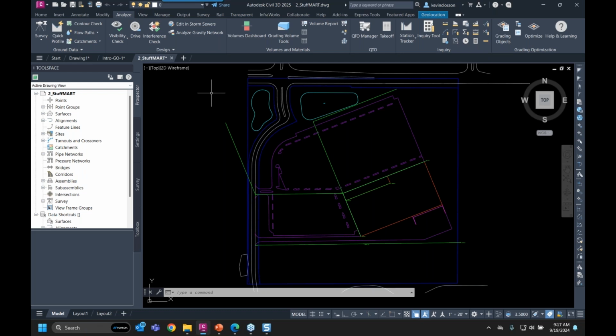And once that was in place, then we would start going in and projecting all of these different lines up to the surface, the parking, say the islands here and there, and whatever it may be, and then project all that information up, turn it into feature lines, and then start manipulating the surface from there, keeping it on the same grading sites, et cetera. So I've spent more time doing this. It can be a lot of work, and then at the end of it, we're also managing multiple surfaces to get this thing.